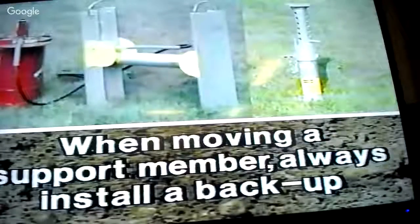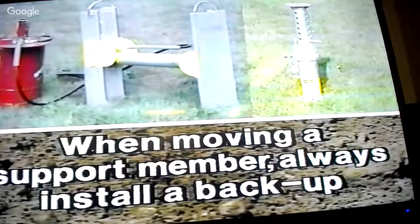That way the employees involved are not going to be exposed to unprotected excavation. And the same goes for when you're removing these protection systems, the theory being that as you remove them, you're moving up the excavation towards the top, and you actually work yourself right out of the excavation. So it's all based on the employees never being in an unprotected environment. If at any time a support member must be moved, a backup structural member should be installed.